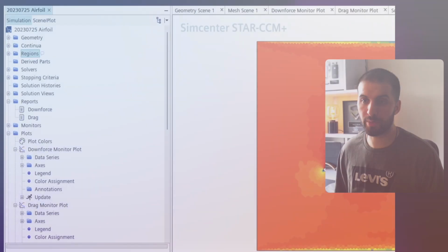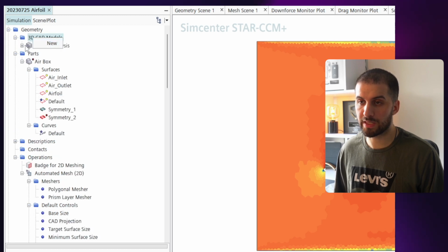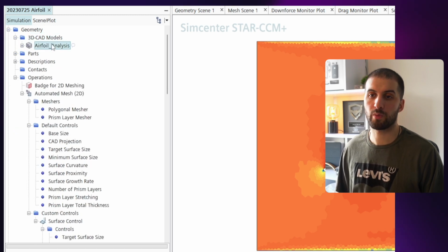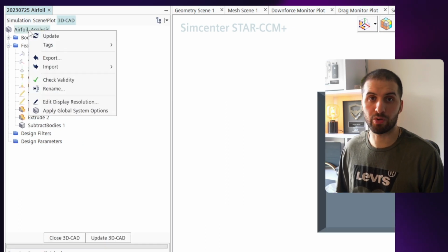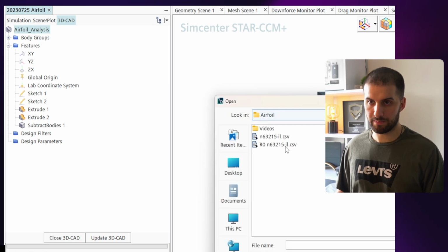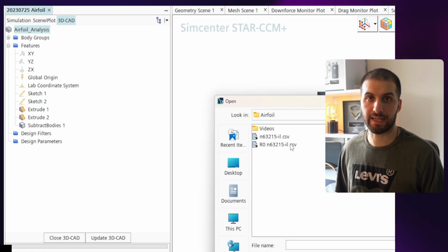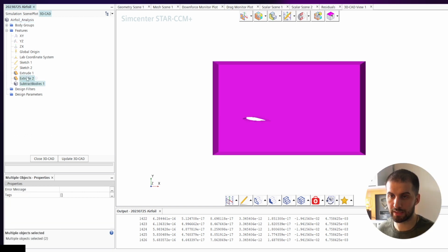So we go to Geometry, create a new geometry, and we'll have this part created right here. Next step is to go to Edit and right click here, Import 2D Curves. Once you are in 2D Curves, you select this file. That file will be opened up as a text. So I'm going to show this to you very quickly. So we will get only the sketch.